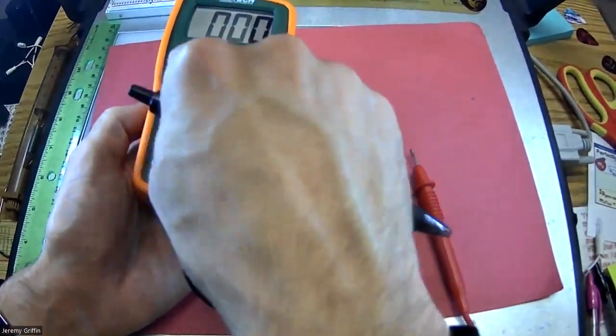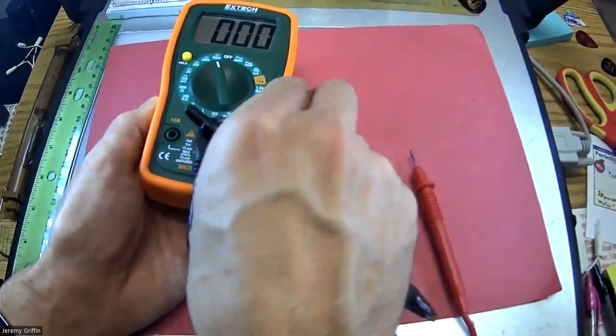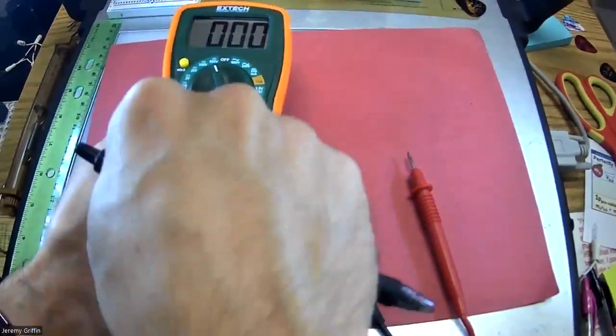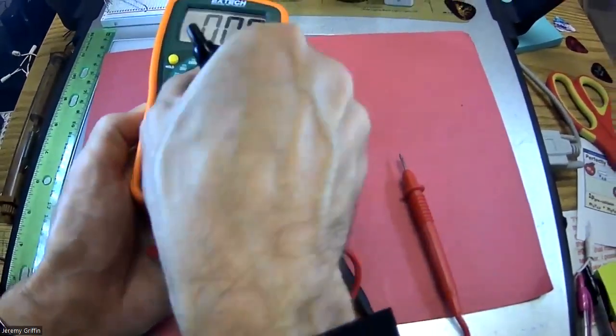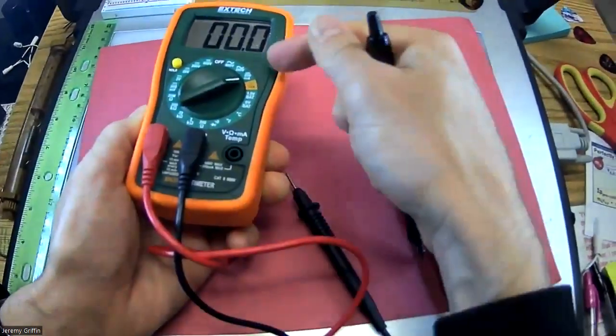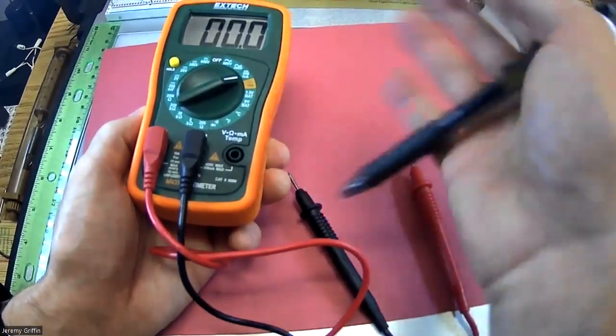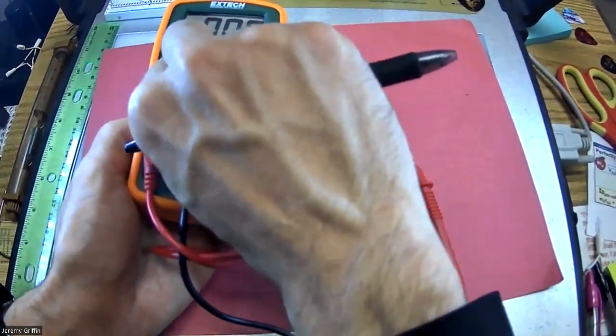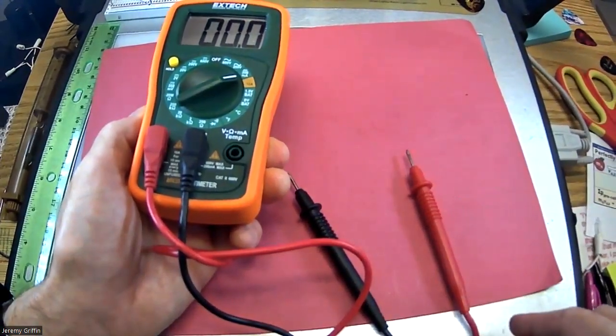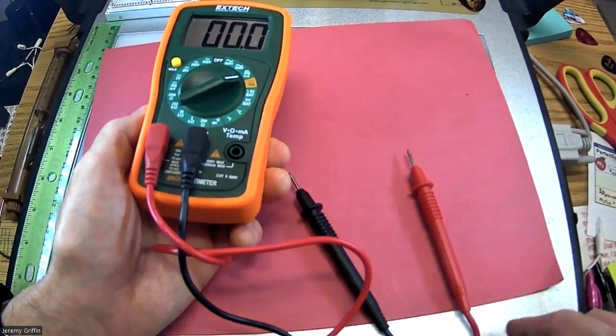But if I want to switch to current, I got to make 2 changes. I got to pull this out, pop it in here, so one says amps, and then switch this toggle over. There's 2: this one says milliamps, one says amps. So I think it's just a decimal place thing again, right? Something to do with amps. How many amps? Like an ammeter for the current.